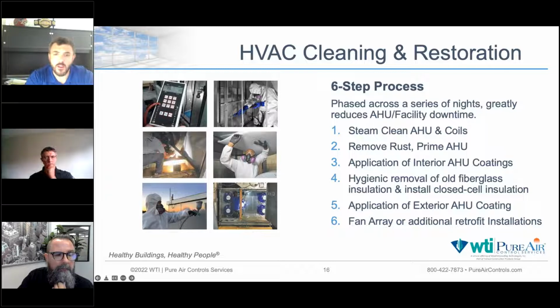You start out with a deep cleaning of the air handler, all components of the air handler, including the blower, the coil, and the internal cabinets. If the coil has a high static pressure drop across it, or it has some physical damage or is leaking, then the coil is just replaced instead of being cleaned. But if it's not in such a condition and we think we can get great airflow across the coil from our process, then we're going to keep that process up.